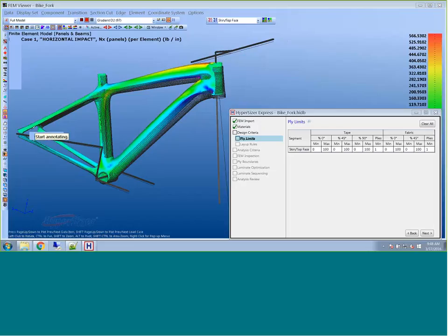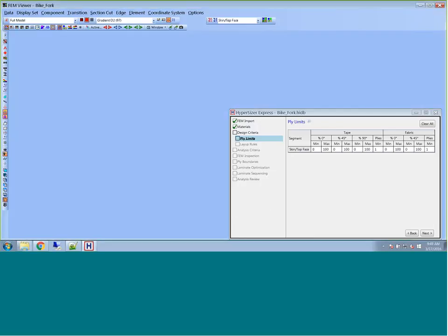In this load case, we fix these rear points here, and we apply a load at this node, and we want to minimize the deflection in this direction of that node. As you can see, the load introduction to the structure that we optimize can be done using other elements like bars and trusses.